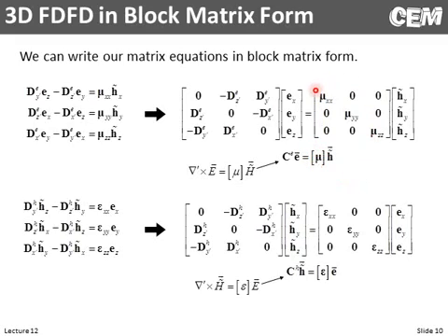The reason that we're maintaining these diagonally anisotropic terms, the diagonal terms through the tensor, is so that we can incorporate our PML, our uniaxial PML, which is anisotropic. And from last lecture, we know now that we can put things in these off diagonals, but we have the extra complication of the interpolation matrices, so we're not going to worry about that here. We're just going to assume diagonally anisotropic, and we did that to accommodate the PML.